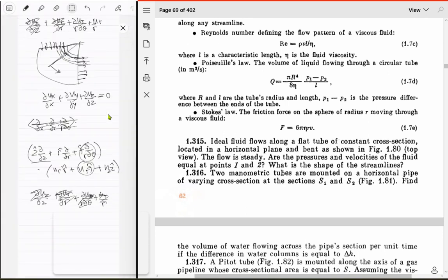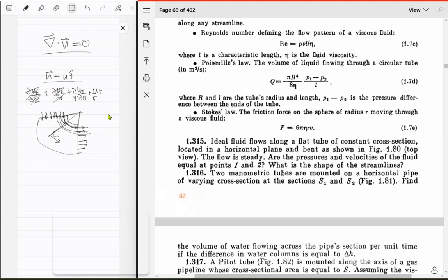The vorticity being 0 is not a test, it's just something that you can use, right? So we don't care if the vorticity is 0 or not, so we don't need to do the curl operator. So yeah, this is it. Which means this looks like something that could actually happen. And yeah, it meets the boundary conditions as well. It meets the continuity equation, which was just this thing actually. So it meets that everywhere and looks good, no big deal.